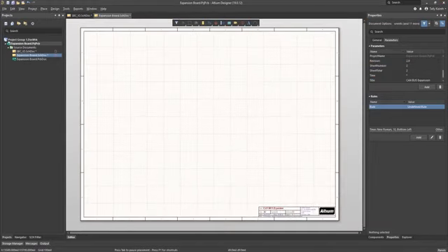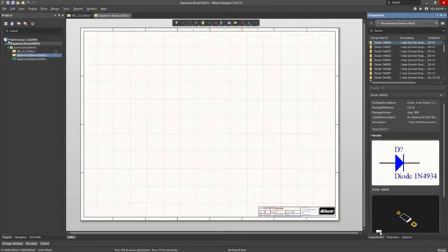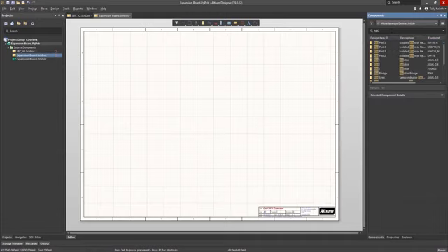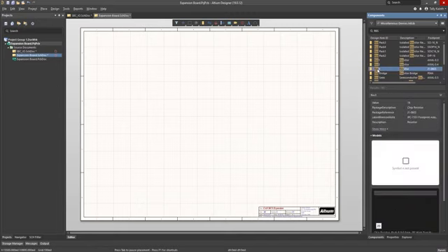We can now start the process of adding components to the schematic from installed existing libraries. We will place a surface mount resistor from the Miscellaneous Devices library, which is pre-installed with Altium Designer. To speed up searching for a particular component, we can enter the part name, in this case, Res. This causes the components with Res in their name to be displayed and highlighted. We will pick the surface mount resistor Res3.